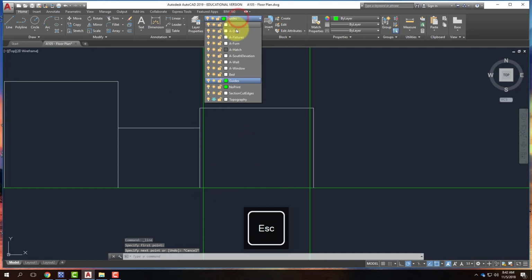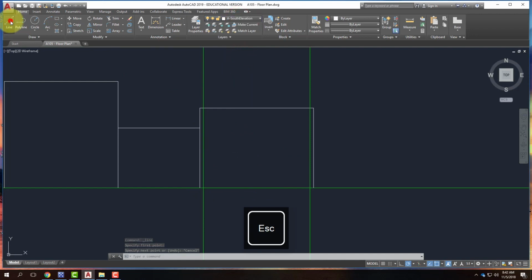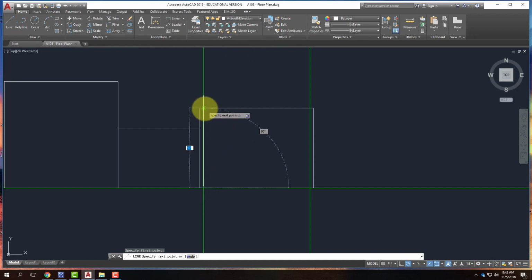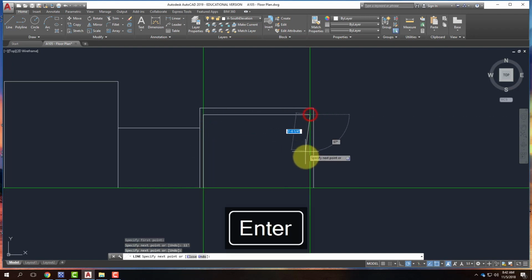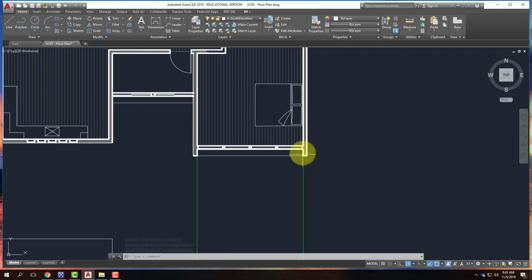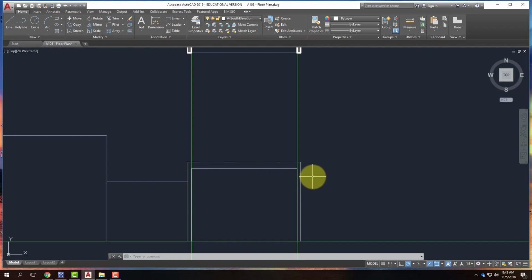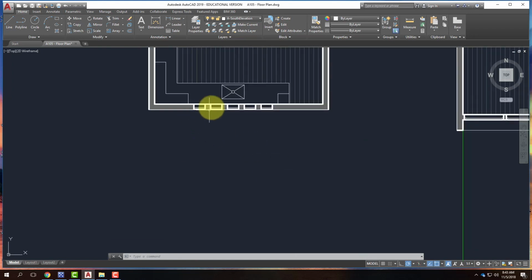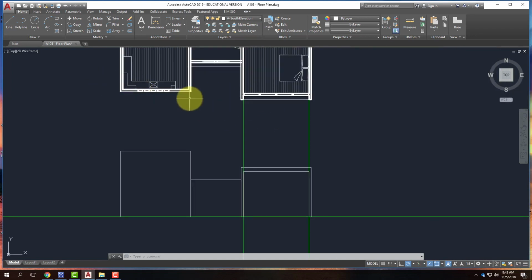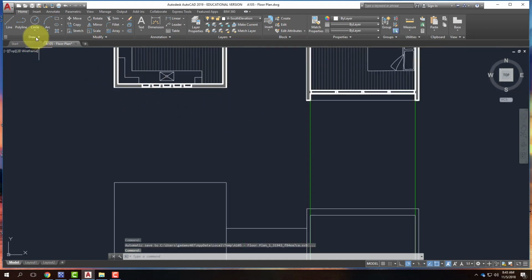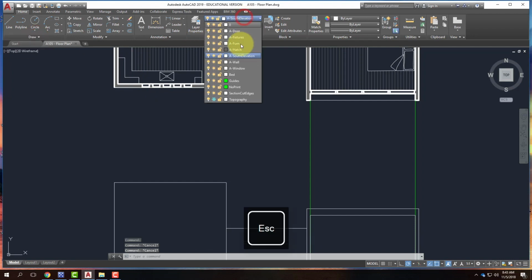Oh, I should switch into my south elevation first. And I'll draw a line that goes up. I'll say that there's a foot of roof up above here. So I'll draw this line at 11 feet. And I'll come across, and I'll come back down like that. And so that's then identifying the wall that's sticking out right here, and the wall that's sticking out there, and the overhang that comes across the top right there. If I move to this wall, what I have is a series of windows and nothing else. So I will use the ray command again. And again, I'll switch back into my guides layer.